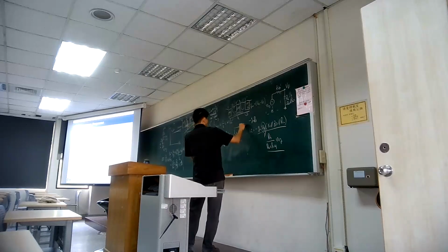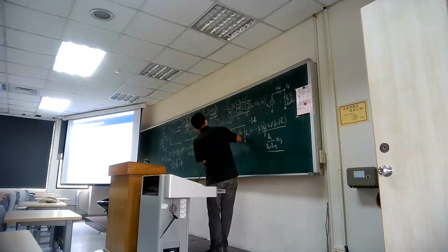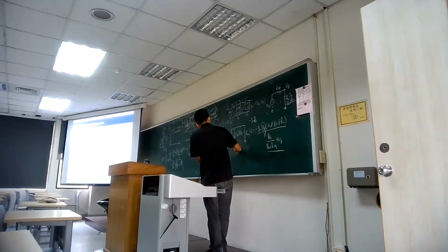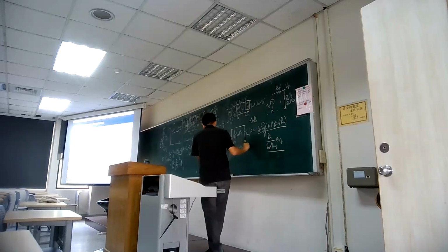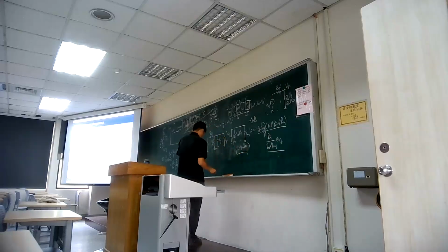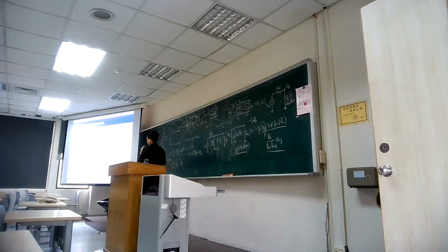Here is CGS. And then we have RDL, the output equivalent resistance. And the CGD here is CGD multiplied by 1 plus gm RL. Okay. So actually, we can separate the capacitance into parts using the above Miller effect.